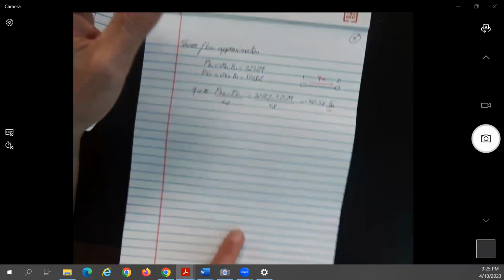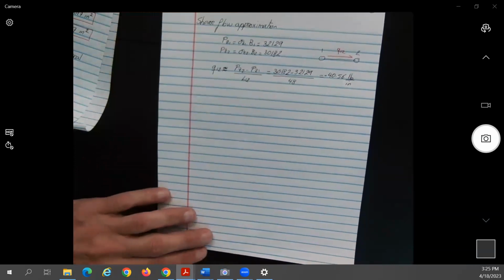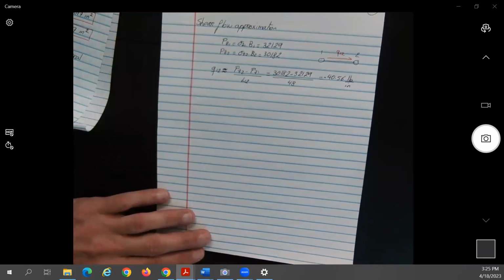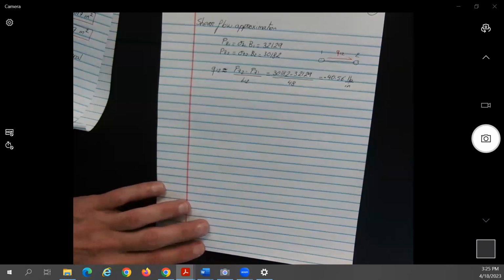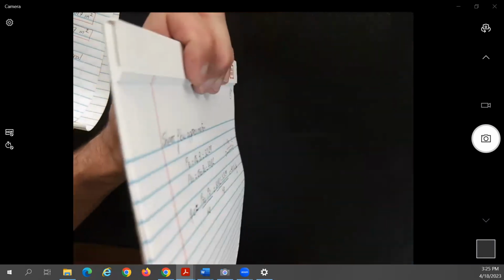Okay. So buckling is a complicated problem because it's not really a structural problem from the point of view that the structure is slowly deforming. It's not proportional to the force, no? When I keep the notepad this way and keep pushing up, you put force, but it's not deforming. As soon as you reach a certain force, then it buckles.